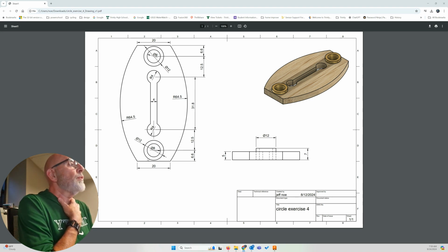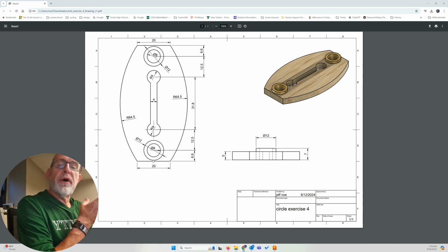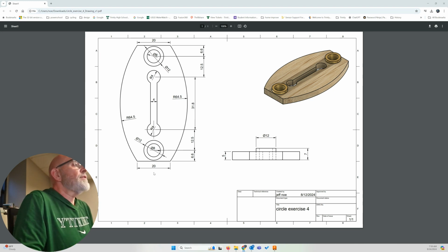Okay, so we'll do sketch dimension. We'll position them 70 millimeters across. From the midpoints, so this will be the vertical axis. From the midpoints of each line, we'll draw a construction line down. That'll help us center our designs here.